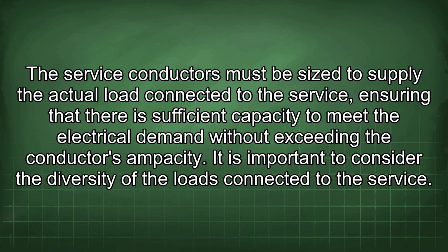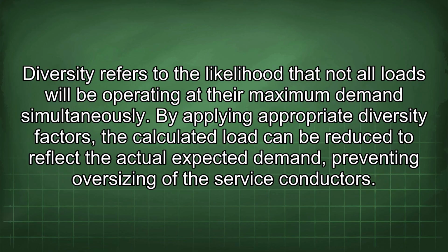It is important to consider the diversity of the loads connected to the service. Diversity refers to the likelihood that not all loads will be operating at their maximum demand simultaneously. By applying appropriate diversity factors, the calculated load can be reduced to reflect the actual expected demand, preventing oversizing of the service conductors.